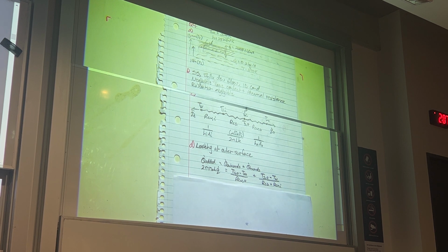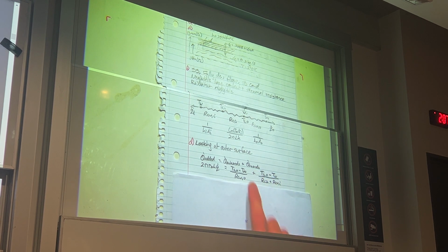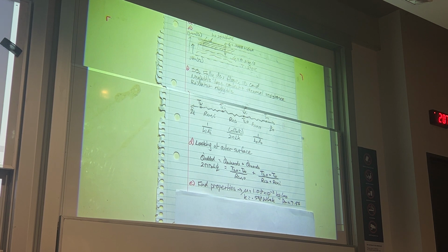So our next part is to determine the heat transfer coefficient for the water flowing through the Teflon tube. What you would have noticed is up here we're given everything except the h_i, and we can't solve this equation yet until we get h_i. So we want to find all the properties of the water. Yep, so we use this table here, and we're at 290 kelvins.